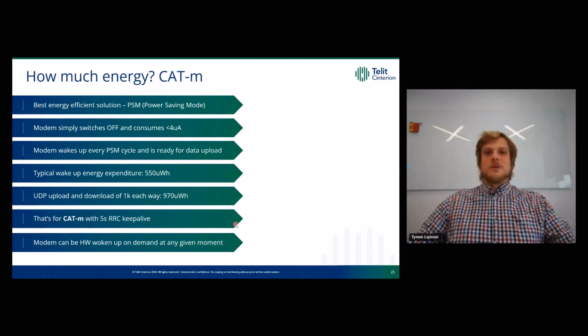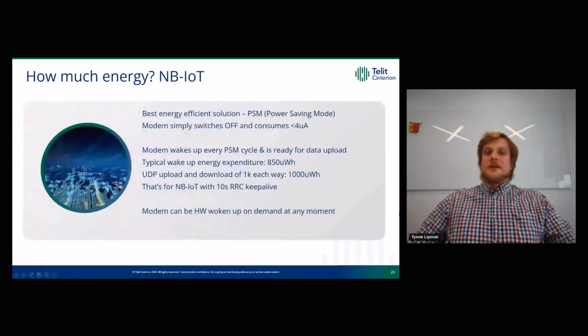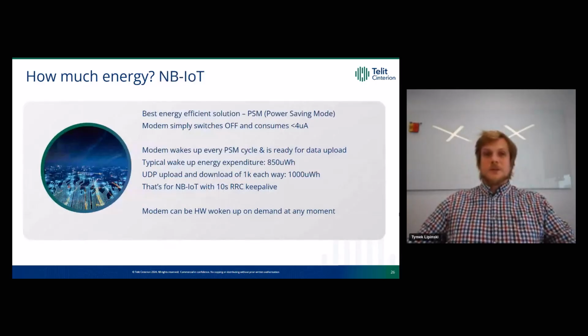Of course, when the modem goes into power saving mode, we can push a button and the modem can be hardware woken up at any given time and proceed with data. Let's compare it to NB-IoT. So, the best energy efficient solution, again, the PSM feature for NB-IoT. Again, the modem simply switches off and consumes below 4 microamps just for running the RTC to know when to wake up. Typical wake-up energy expenditure, 850 microwatt hours.